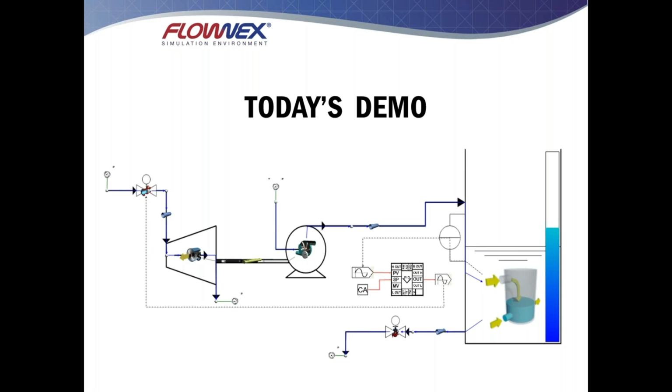There's quite a large delay inside of this system. Adjusting the valve position is going to ultimately adjust the flow rate of steam through that pipeline, which will change the power into the shaft. This will either speed up or slow down the turbine pump arrangement. Then that pump will either increase or decrease its flow rate into the tank, and that will ultimately affect the level inside of the tank. So there are multiple layers to this control network.